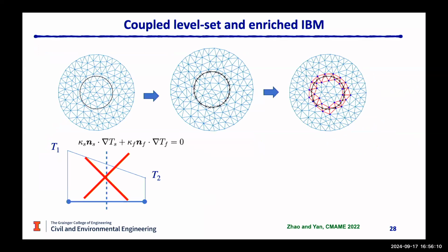Okay, I see. So your level set triangulation is pretty much like adding some nodes along the element edge, so it won't cross the element node. That's right. Those nodes for the triangulation, or those crosses, are on the edges of the background element. They are never going to be inside of the interface. But for the conventional immersed boundary method, it's not guaranteed. The node of the immersed surface can be in the interior of the element, and sometimes they can cause some instability issues.